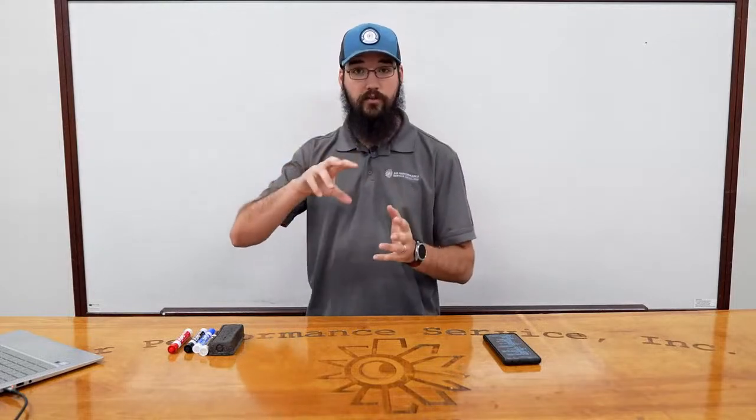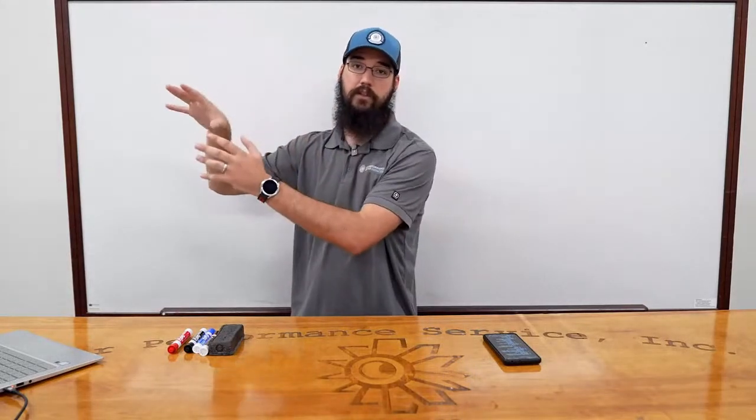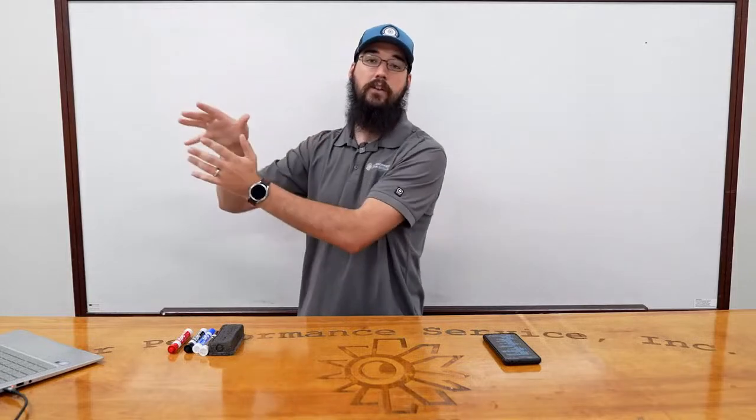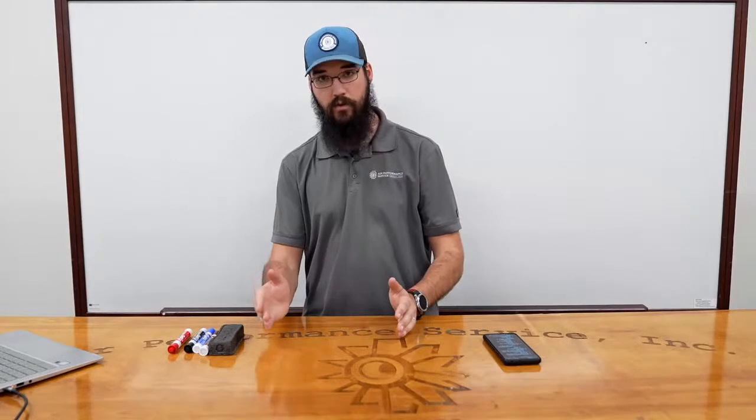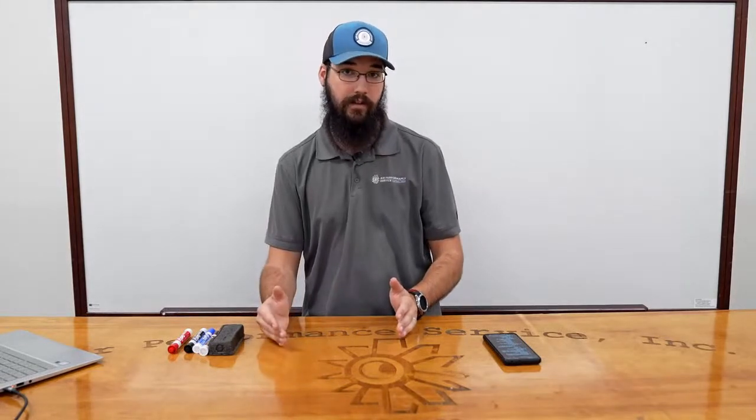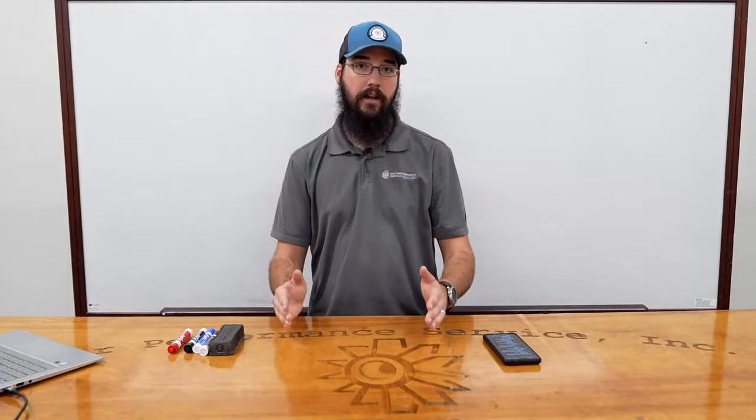Legitimate industry high static systems are 2, 3, 4 inches of static, and they can get real specialized, and the industrial side of things uses a lot of that. When I'm making a difference between a high static and a low static system, I'm making a separation between the large commercial systems that run 1 inch of static on the supply side of the duct, with a really high external static compared to an RTU, for example.